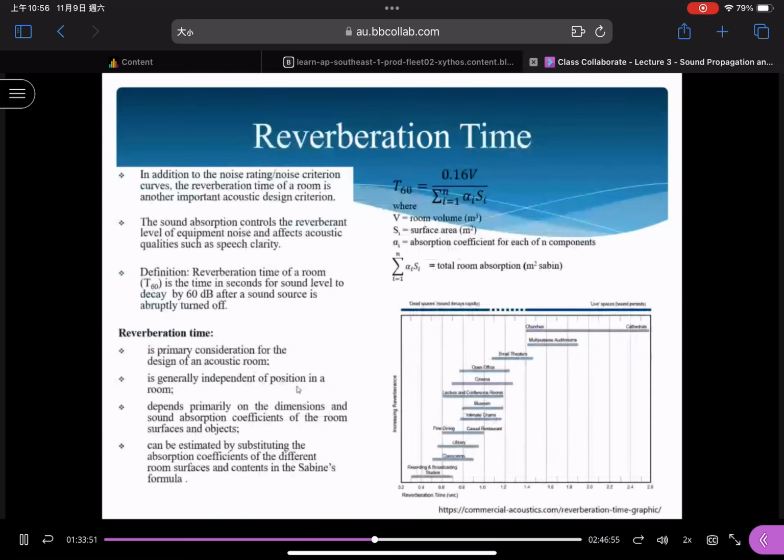Okay, any problem? Another way is that we can use the reverberation time to find out whether the design criteria can be fulfilled. This is a chart showing different classifications, such as office, building, cinema, or something else; you can make use of it to decide the effects. T60 is the reverberation time. This is the equation to find it. This is A, the total absorption. So we can write it as 0.16 times volume divided by A. V, the capital letter V, is the volume of a room.